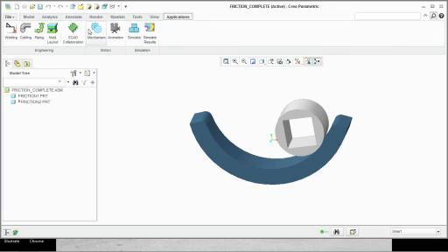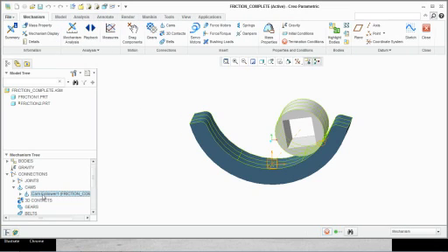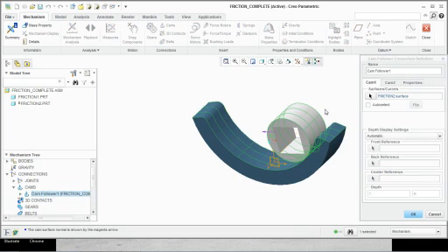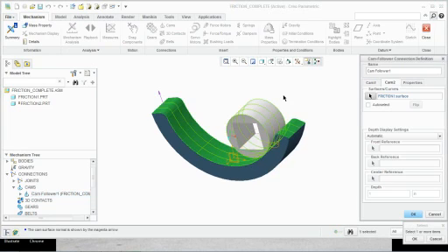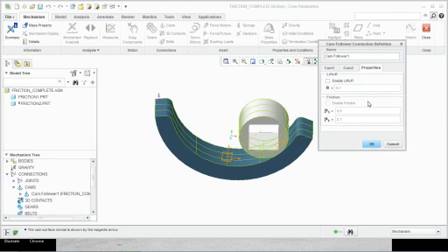So here I want you to see that there is a cam connection. I'm going to edit the definition. Notice that you pick a surface right there, the cam surface, and then you pick another surface. Those are the two surfaces that I use for the cam. Now this is the most important part. I'm going to disable all these.